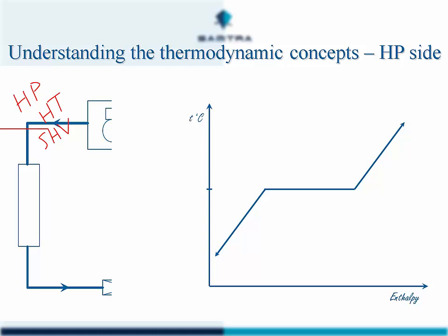So as it goes into the condenser, we're going to have a certain amount of what we would call de-superheating. Once the refrigerant has reached the temperature where it will condense, condensation will take place. So condensation will occur until we have at some stage 100% liquid in the condenser.